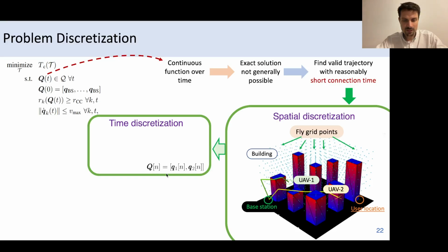So with this notation, this means the configuration point at the nth time instant, or sampling time instant, right? Then what we now have is no longer a trajectory, like the position for every time t, but only a sequence of configuration points, right? So this is what we call a path. So trajectory means continuous time, and path means discrete time.